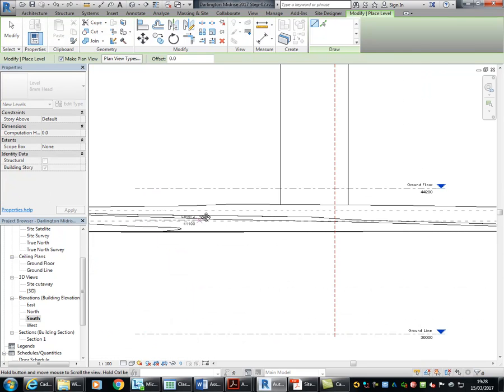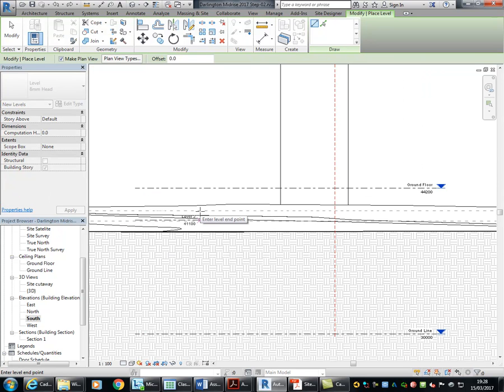ground floor. So remember, left to right is usually a good thing with levels, simply because it puts the tag on the second point. So if you go left to right and your tags are all on the right hand side, it's just going to make sure the tag goes on the same side.